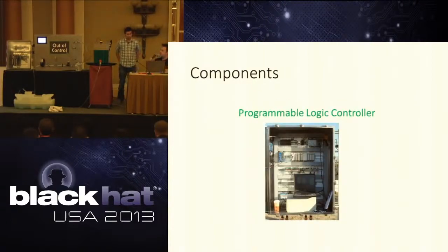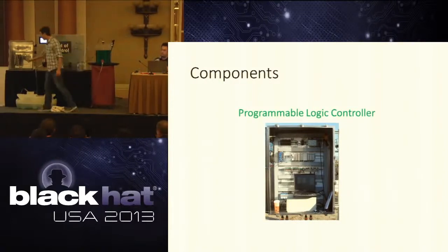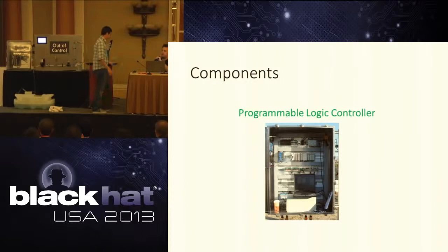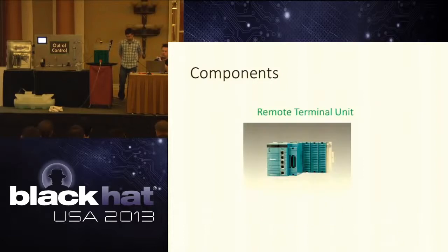The PLC is, do you want to point that out? Yeah, sure. So the PLC, they're called PLCs, controllers, or RTUs, remote terminal units, but it's this guy right here. He's what actually controls the process. A PLC takes inputs such as a temperature sensor, or in our case a level sensor, and has logic that it acts on those inputs and writes outputs to the system, which controls a pump or a motor or a valve, things like that. An RTU is very similar to a PLC. It might have some more capabilities and more logic available.